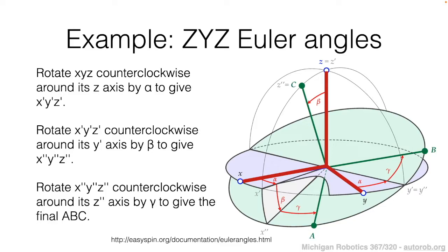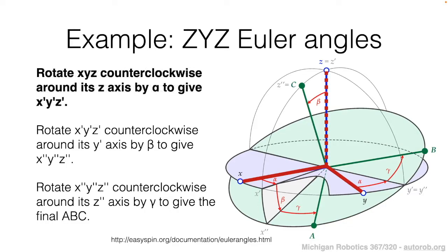So let's look at this to start with, and let's say that we begin by rotating this coordinate frame about the z-axis by alpha degrees. The axis of rotation, since it's the z-axis, is shown now as the dashed red vector. And the rotation by alpha degrees then is going to result in this transformation that we just saw.